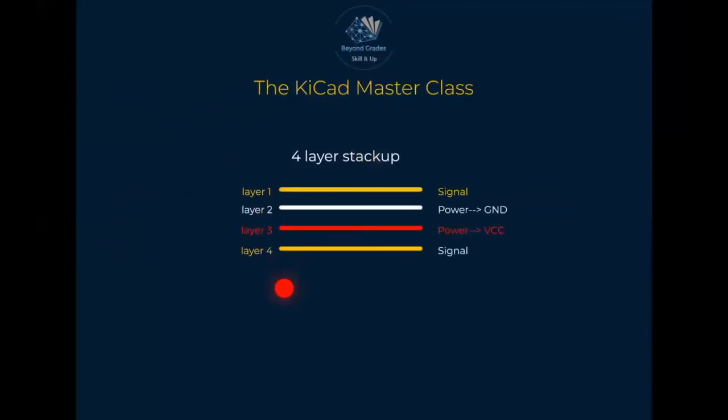So let me touch on a four-layer stackup. What do we mean by a stackup, and what are the advised practices for laying out a four-layer board, and where do we choose such stackups? When we have a four-layer board, the top layer, which is layer one, should always go for signal layers. I'm talking of any signal within your board, any connection that's not power and not ground. Like signals communicating between different ICs, say from the MCU to some other component. And of course, we always try to fill as much as you can of your signal layers on the top layer.